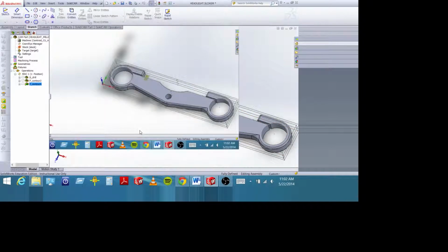And you should be able, after today, you saw how to zero your tools and your XY zeros in your coordinate systems. Remember, this part's going to take a long time, and you only have the next week and a half to do it. I would strongly recommend that you try and set your tool zeros today, either during Open Lab in the 3rd segment or during shop time 12 to 5.